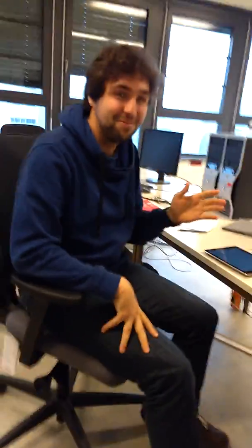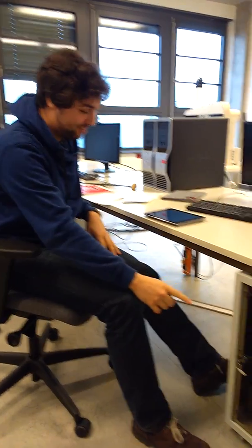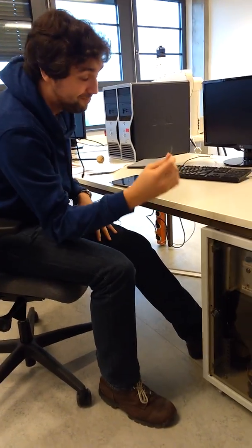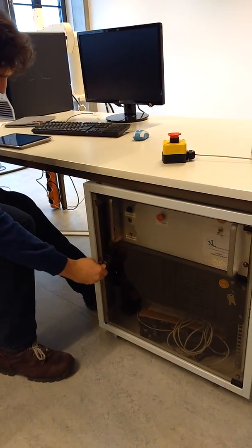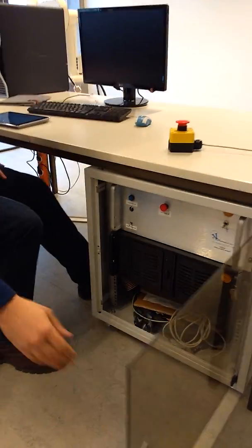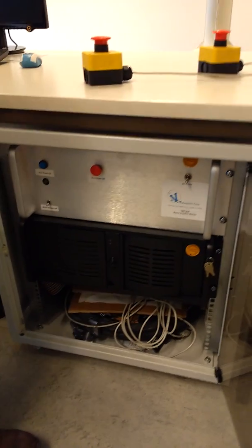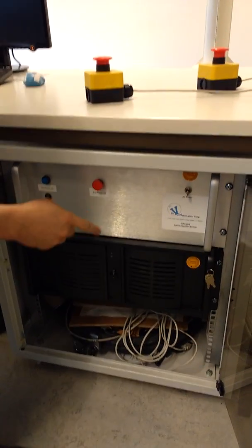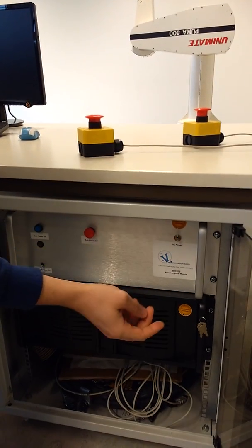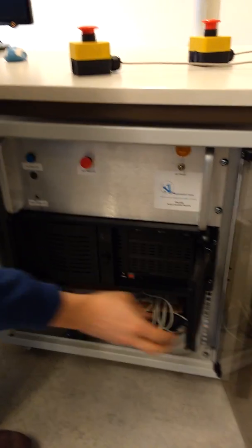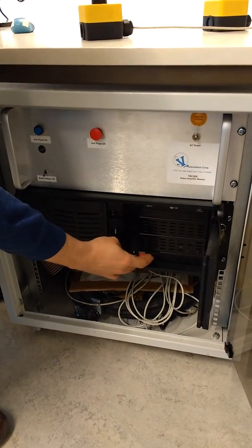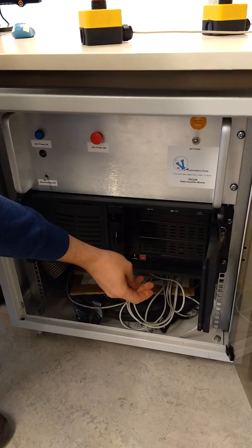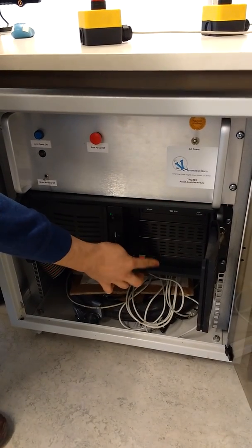All right, so we're going to start the PUMA now and do the whole process. First, you need to get the key for the PUMA box from the secretary. And open the PUMA box, and in here there's the amplifier, power for the PUMA, we can start that one. And down here, that's the QNX box, there's a power button here. And if you actually push it, it's going to start booting.